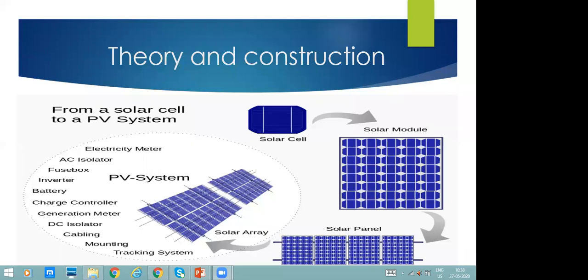Solar cells must be protected from mechanical damage and moisture. Most modules are rigid, but semi-flexible ones based on thin film cells are also available. These cells are connected electrically in series, one to another, to reach the desired voltage, and then in parallel to increase the current. The wattage of the module is the mathematical product of the voltage and the current of the module.